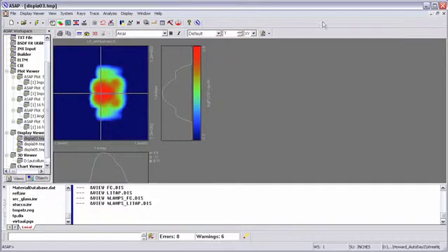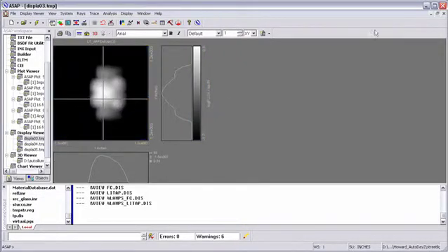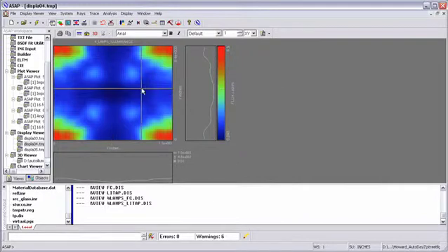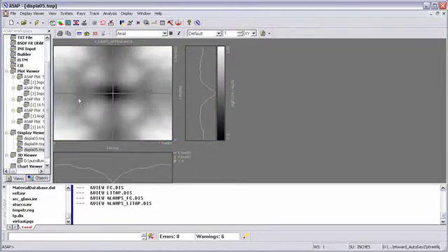We also have each one of those plots in a 2D plot viewer where we can go in and interrogate each pixel individually and find the values of the points. Now, this particular plot happens to be a plot that's been adjusted to simulate what you might see with your eye, as though you were hovering above the pattern. This is a nice isolux plot of the 4 lamps, and then this is the plot of the 4 lamps positioned over a roadway section.